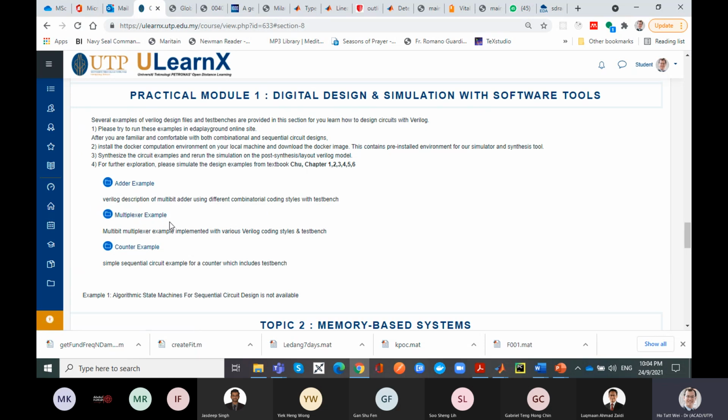That's why I like to suggest this, because if you have the multiplexer approach for designing circuits, writing the Verilog becomes almost like a recipe already. You don't actually have to think very hard about writing the Verilog. It's sort of like how McDonald's is able to make great burgers because they have a recipe that any franchise can follow. So if you can frame your circuit as a multiplexer or lookup table, the Verilog is almost just like a recipe. You just follow it, you fill in the blanks, you know how to design it. Okay, that's why I'm going to focus a lot on the multiplexer and lookup table approach to designing digital circuits.